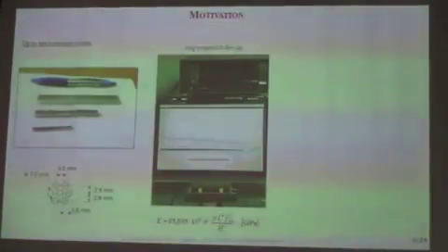I checked the bending behavior of these rods by performing vibration experiments. There is a free boundary condition, and when there's an impulse, it starts to vibrate, and by a microphone I get a fast Fourier transformation.